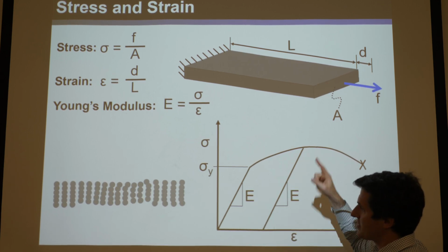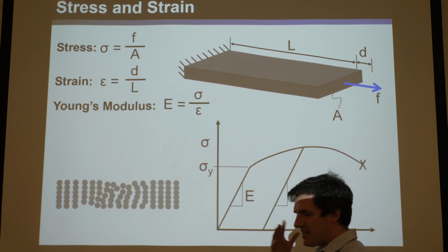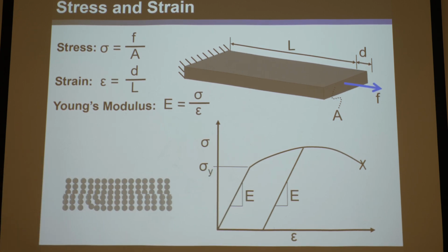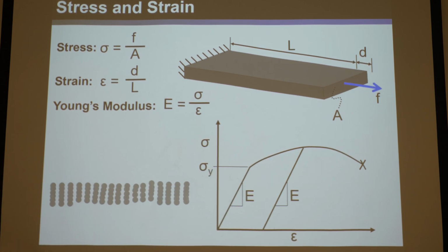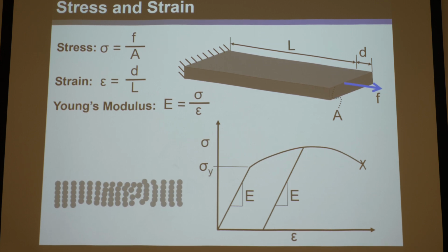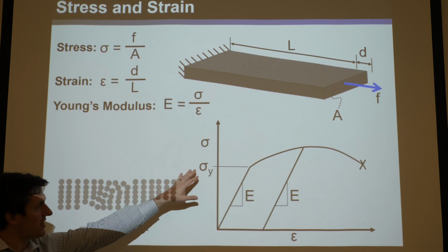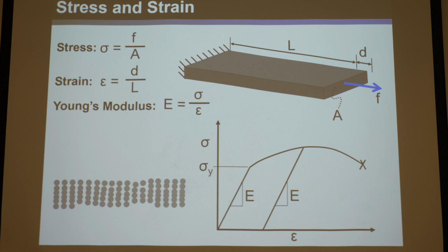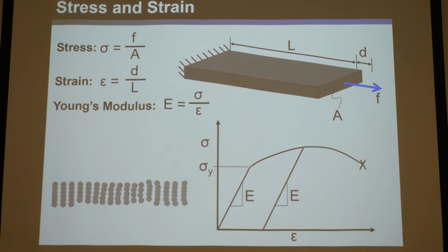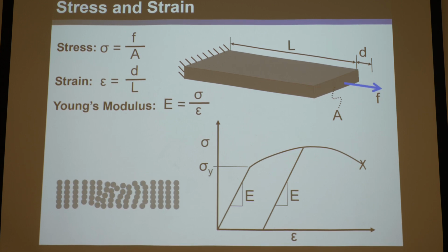And you can get these loops and things behave. If you loop it many times, you'll see it behaves slightly differently each time. It does settle into one nice kind of loop, but you need to know how many loops have been done in the past, and it's not a repeatable process, so it's bad for precision. So you generally want to stay away from yielding, right? Okay, so that's yielding, hysteresis. That's just some mechanics there, a little review of precision.